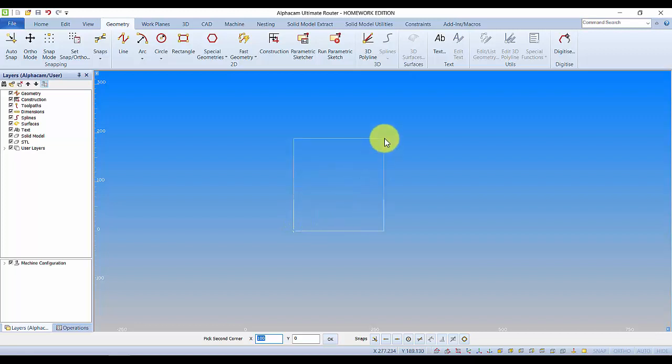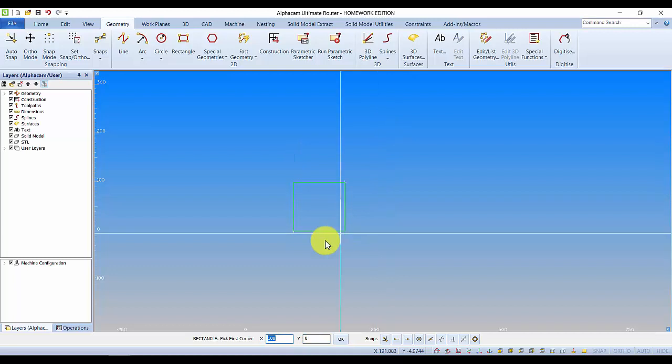If you're ever unsure about the coordinates, I know I want to put the mouse cursor approximately here. I want that to be 100 by 100. So move the mouse cursor approximately where you want it, and it should give you an indication down here in the automatic or the real-time live coordinate box. But I happen to know I want to put in a value of 200, tab 100, enter.